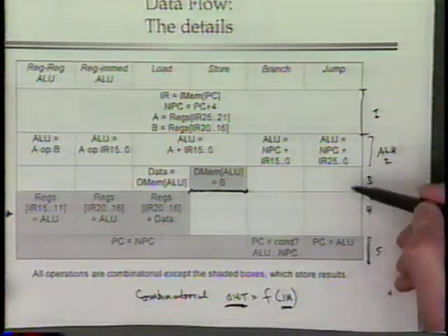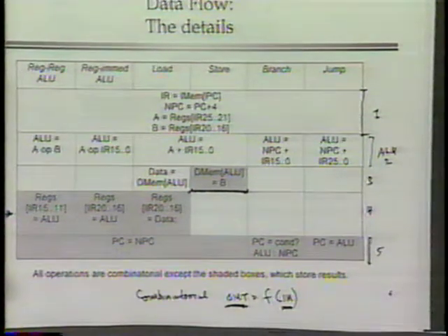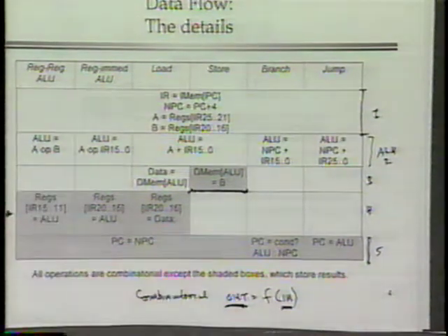We can clearly define the demarcation points and put registers saving state information in between them and build our pipeline machine. Why might this not be the most ideal pipeline for DLX? Anybody have any guesses?